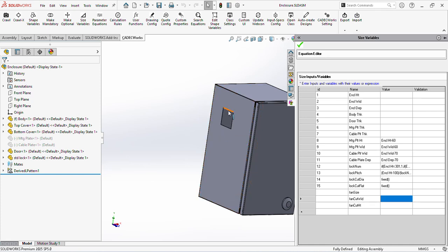This fan cut has a height and width, and it changes based on the fan size chosen. So for fan size, we'll choose a validation fixed. So it is a size lookup that we'll be defining. And in fan cut width and fan cut height, we'll specify the expression as fixed, and in bracket we'll specify the variable which drives this fan cut width, which is fan size.